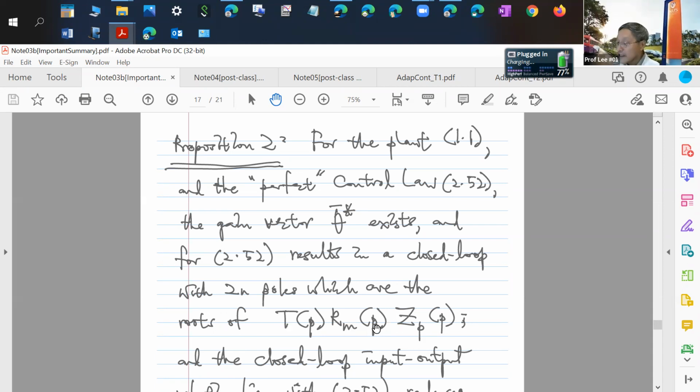But in the way that we are working in this system, the ZP is a constraint we have to live with, because the 2n closed loop poles are also at ZP. ZP is the set of zeros of the system, which means that this approach is constrained to work with systems with stable zeros, the so-called minimum phase systems.